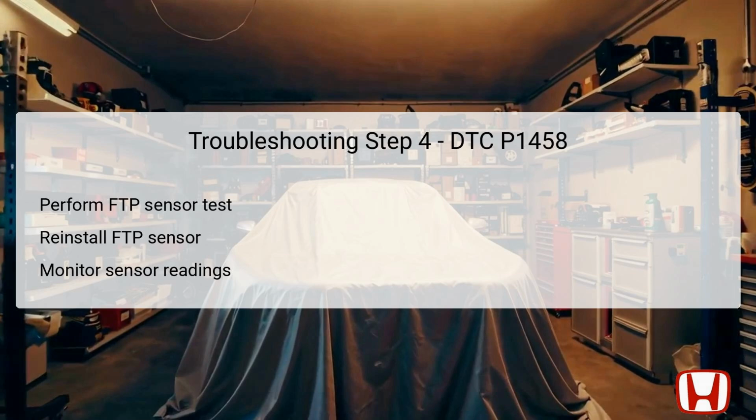Under normal conditions, the sensor value should remain stable within a certain range, not deviating by 0.067 kilopascals or more in a 3-second interval. If the readings fluctuate significantly, this suggests a malfunction in the sensor, which may warrant further investigation or replacement. Aligning with these readings confirms whether the FTP sensor is performing within its designated parameters or highlights the necessity for further action in the troubleshooting process.